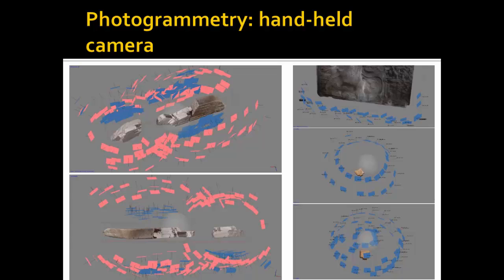The most common technique is the so-called structure from motion. An observer positions a camera at different angles, but also slightly different viewpoints in relation to the documented object. And then specialized software derives measurements, a cloud of points that corresponds to the topography of the object, based on differences in angle and positioning of the camera that captured the photograph.